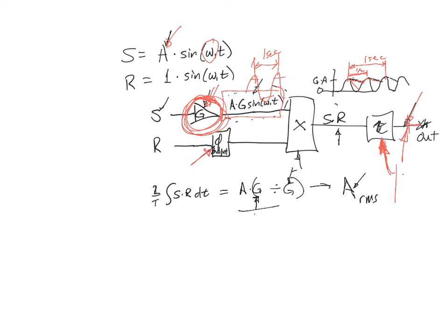So the output will be one DC level, and then you change it, and it's going to slowly creep up to the new value. And if that takes several minutes, you're going to get annoyed. So generally, unless I really had to, I wouldn't set the time constant longer than 1 second, because I don't like to wait longer than a few seconds to get to a new value. Okay, so that's the time constant knob that you're going to need to set.